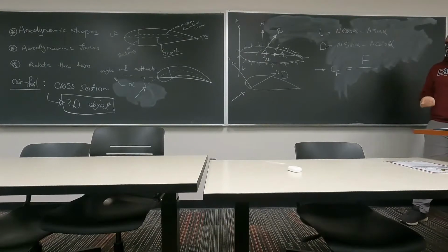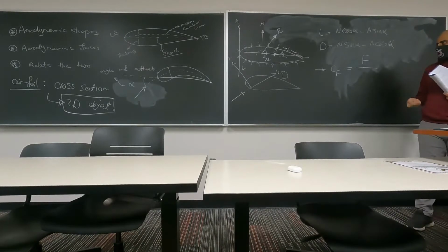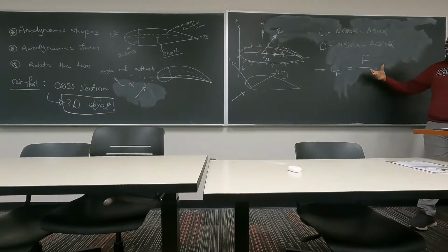If you had done any dimensional analysis, you would have known that we usually take a parameter here to normalize your force, to non-dimensionalize the force, that doesn't change with your flow. That's like a characteristic of the flow. Like if you were non-dimensionalizing velocity, you would have used free stream velocity. Free stream velocity is something you define, right?